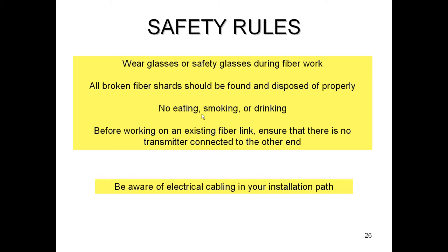Now, testing of fiber can be very simple. A simple flashlight held up to one end of a fiber optic link, if it goes through to the other end, a simple flashlight will go through 4,000 feet of fiber. If the light comes through the other end, that's telling you the fiber's not broken, and chances are it'll work just fine for the application of physical security devices, because even if it's a box that transmits 4 or 8 cameras, you know what? We are not really taxing the bandwidth capability of the fiber. I'm not telling you to take the short way out, but what I am telling you is that if you test it with a flashlight and the light goes through, you know the fiber's not broken, and chances are you can hook your equipment up.